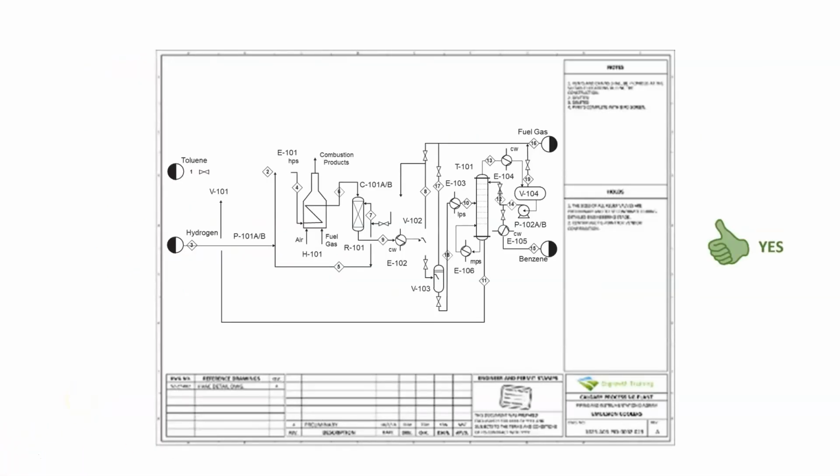This is a very good example of a high quality PFD. You can see all the major equipment and the process streams are on the sheet, plus the major and essential valves. Also, as you can see, it is developed left to right, top to bottom, and it is not to scale. Remember, a PFD is not to scale.